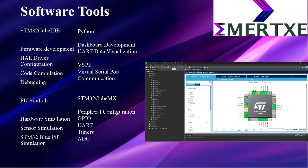Python was used to build a real-time dashboard that displays all the vehicle parameters. VSPE was used to create virtual ports for UART communication between PICSimLab and the Python dashboard. Together, these tools helped me complete the entire project in a simulated environment. Going to the next slide.